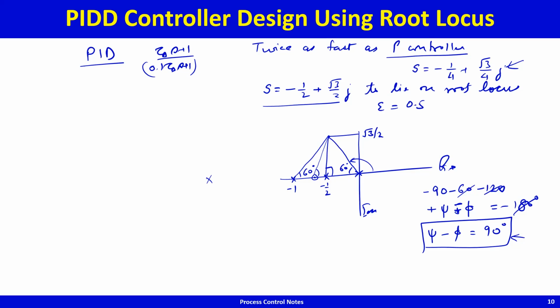If I choose a tau d over here, the angle because of that would be 90 degrees, but the angle because of this would be some negative number, and so the net angle will be 85, 80, 81, 82, 83, 84, 85, but not 90, because this guy will be contributing a negative angle.